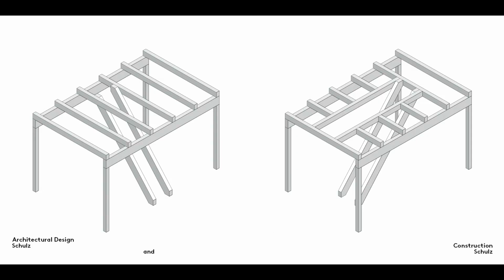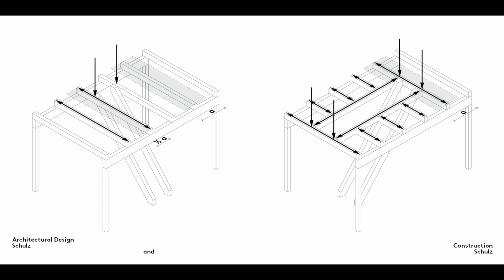The problem is even more apparent when you look at how a floor opening is made in a beam-type floor, such as a timber joist floor, for example. If you compare the installation of stairs running parallel and at right angles to the span width, you can see that the staircase running at right angles to it requires a number of specially cut joists or trimmers, whereas the parallel staircase requires no special adaptation as long as the stairs are no wider than the distance between the floor joists. This is confirmed by an analysis of the flow of forces.